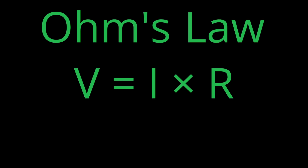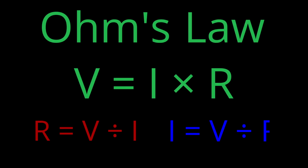Resistor math. Ohm's law you just heard about in the basics section is worth repeating here. I don't think I can overstate its importance. If you go into electronics, you'll run into this equation over and over. It will just become second nature to you. I like to use this visualization of the equation because you can just cover up the value that you want to get, and that will give you the equation you need. For example, covering up R gives you V over I.